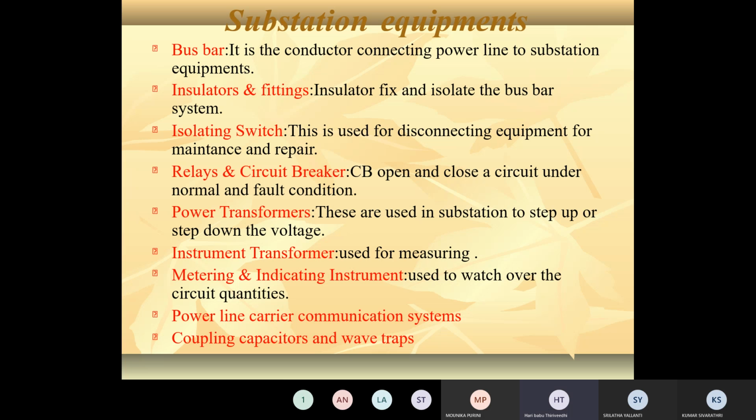The secondary of the CT is always closed. This is the most important point. The CT secondary is always closed. If the CT secondary is open, the winding of the transformer may burn. So that's why the CT secondary must always be closed.